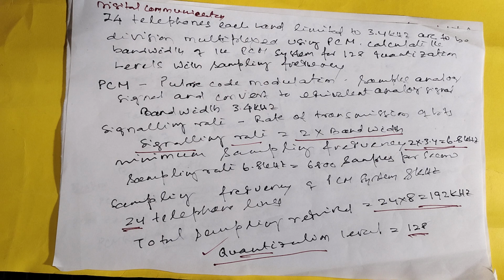PCM produces a series of numbers or digits, and hence the process is called digital. Each one of the digits, though in binary code, represents the approximate amplitude of the signal sample at that instant. In pulse code modulation, a message signal is represented by a sequence of coded pulses. This is achieved by representing the signal in discrete form in both time and amplitude.